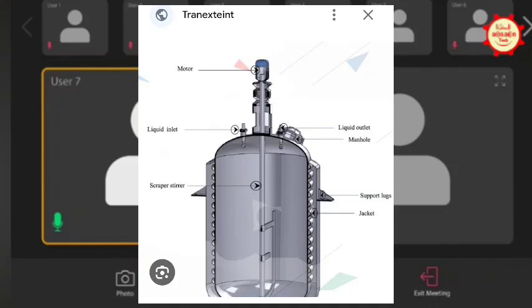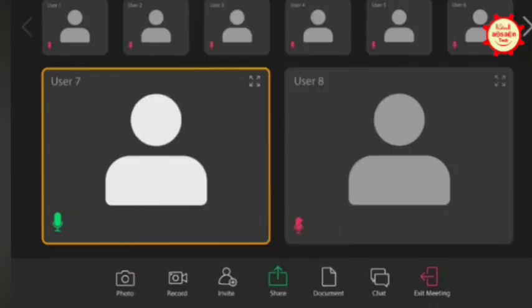One point is the inlet and another point is the exit of whatever fluid you are passing, so you have two nozzles connected at the limpet's starting and ending points. In PVElite you just mention what size of pipe you want to add, its thickness, and the other inputs for the limpet, and it will give the calculation.